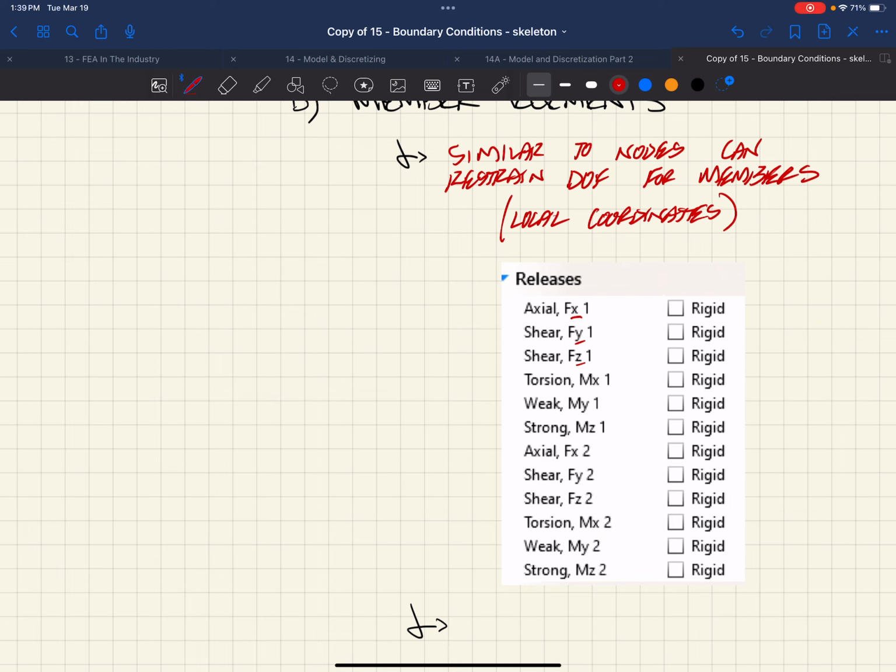And sometimes that shear tab, maybe we want long slotted holes on the ends of it. And so in that case, we probably have shear transfer in the vertical and the horizontal direction, but we have no axial load transfer capabilities at the end of those members, right? And so in order to properly model that connection, we would probably want to release the axial load on that member, right? So we release, say, axial at one end, right?